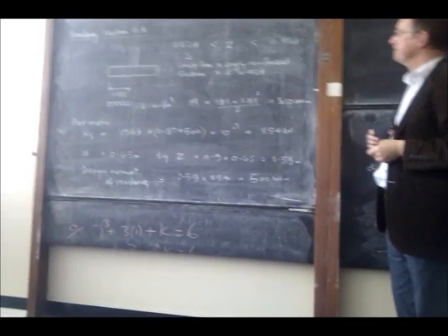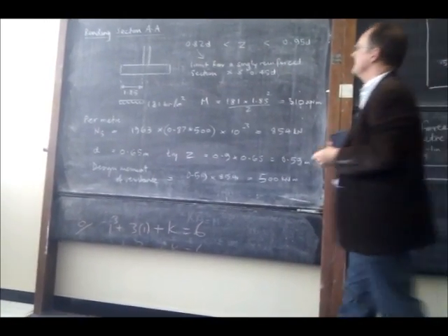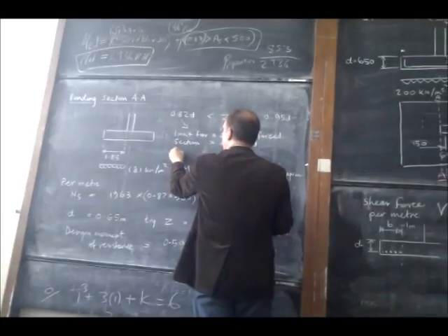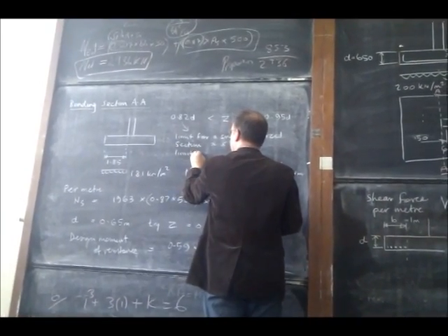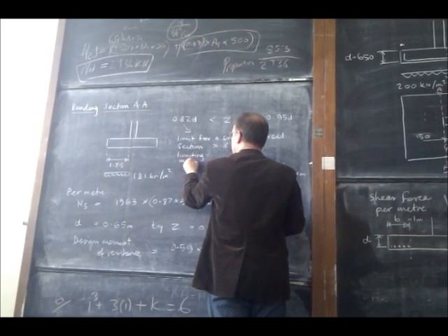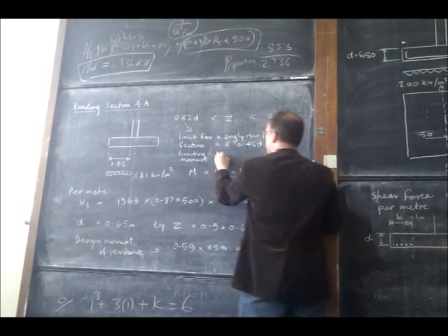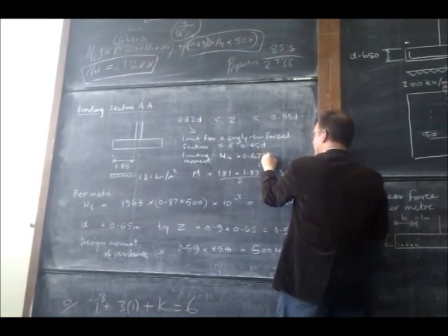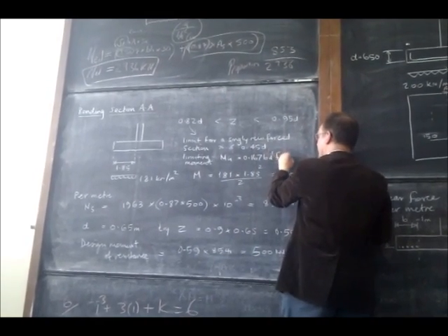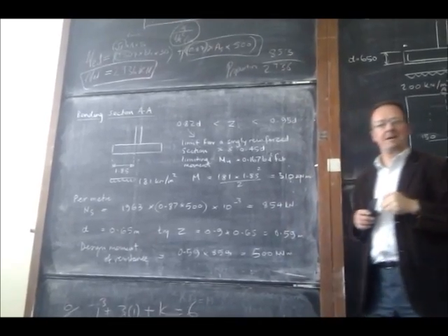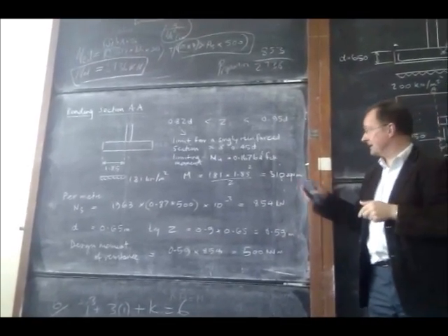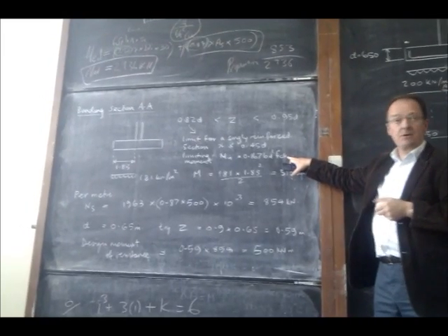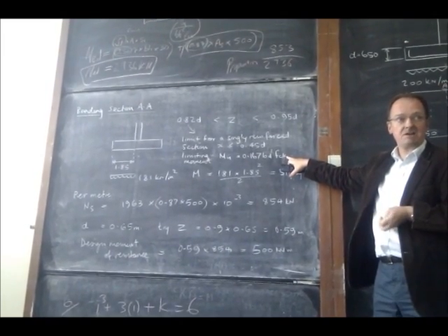And it's also related to that data sheet formula, the limiting moment Mu is 0.167 bd squared fcu, which I rather warn people against using without thinking about it, because that formula is fine for rectangular sections, but it doesn't really work for non-rectangular sections.